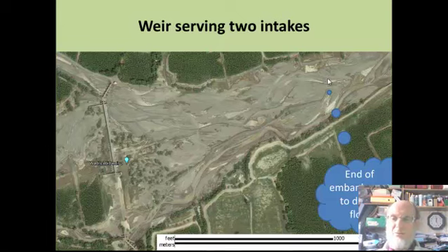So the division point here is about 400 meters upstream of the weir. And this will get moved around from year to year, even between floods, to try and maintain the flow sharing. Not an ideal solution, but it is better than, in most cases, trying to divert water on one side and take it under the wadi to the other side.